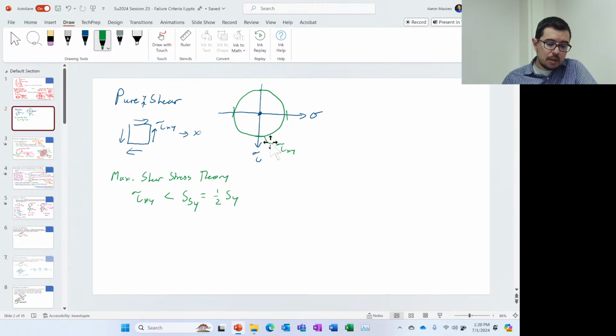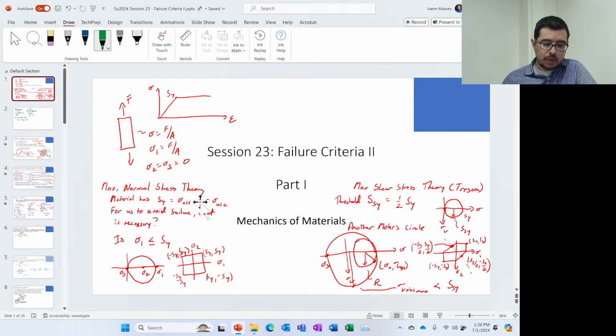So that means that if I've got pure shear, then it's a done deal. I just say tau xy is less than that. But let's say that I'm drawing a sigma 1, sigma 2 plot. Sigma 1, sigma 2 plot. This thing. Usually you don't draw sigma 2 going downward. That's because I was doing the Mohr circle. Okay, there's sigma 2 going upward.